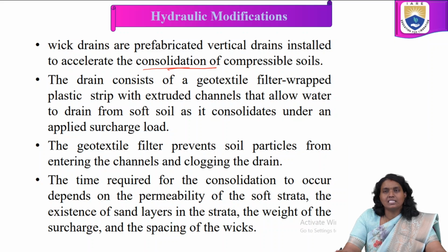The drain consists of a geotextile filter wrapped plastic strip with extruded channels that allow water to drain from soft soil as it consolidates under an applied surcharge load.